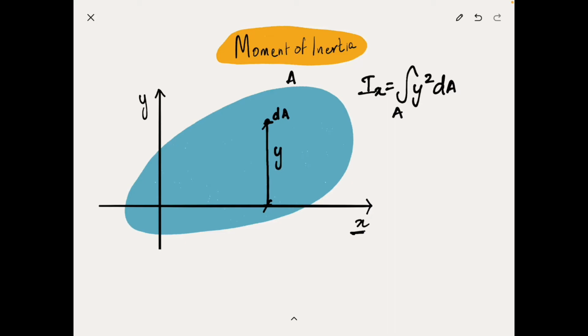To calculate the moment of inertia along the y-axis, we have to repeat the step by considering the distance between dA and the reference y-axis. So if the distance between the reference y-axis and dA is x, then we would have Iy equal to the integral of x squared dA over A. So that's how easy it is to derive a moment of inertia for any given surface. Let's now move on to an example and try to implement this integral to come up with a formula for calculating the moment of inertia for a rectangular cross section.